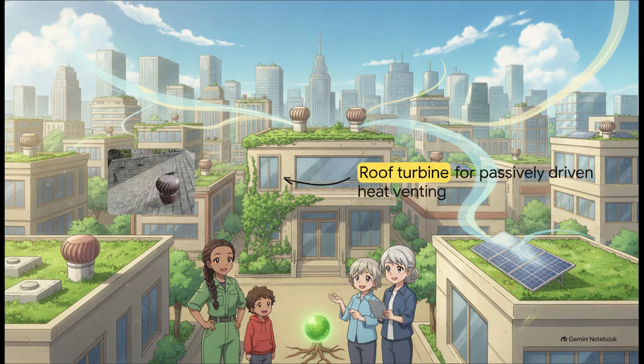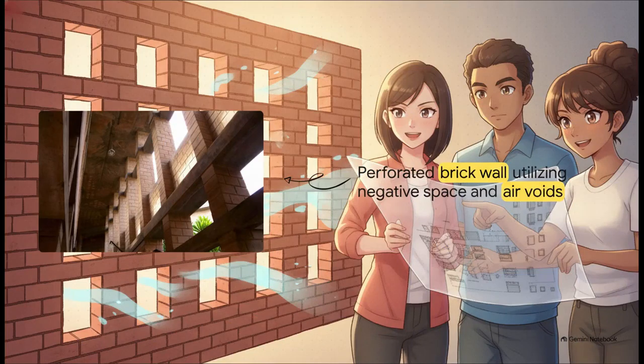How cool is that? And to visually anchor that wall strategy we just talked about, take a look at this remarkable perforated brick wall. Remember when I mentioned incorporating air voids? Well, this construction technique uses negative space, the literal empty gaps between the bricks, to drastically drop the overall thermal conductivity of the wall. Less solid material means less direct solid-to-solid heat transfer through that massive surface area, which keeps the interior shaded and comfortable.